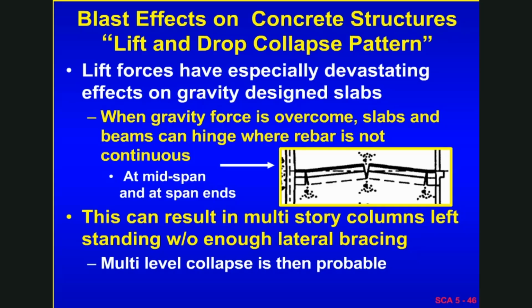Often what can happen in this case is that some of the vertical supporting columns might be left without any floor load on them, and they might be left standing many stories tall with still some load above them and with the chance of buckling, because they would now have, where they were originally braced every 13 feet or so by a floor, they might be standing 40 feet high without any bracing, and we'll show a couple of examples of that.